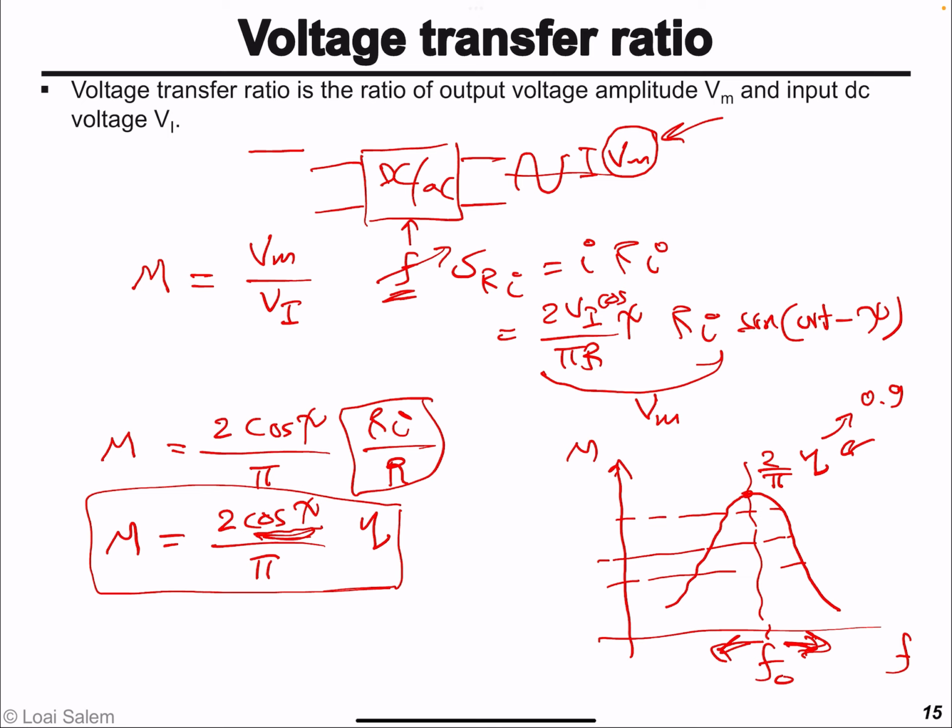That's one observation. The only issue in that is if we are at a specific frequency, say this frequency, and the load resistor Ri has changed. So what will happen is, we know that the quality factor of the series resonance circuit basically depends on the resistor Ri, right?